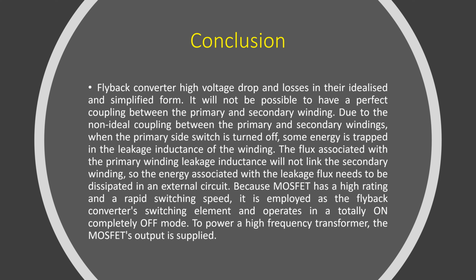So the energy associated with the leakage flux needs to be dissipated in an external circuit. The MOSFET has a high rating and a rapid switching speed. It is employed as the flyback converter's switching element and operates in a totally on, completely off mode. To power a high frequency transformer, the MOSFET output is supplied.